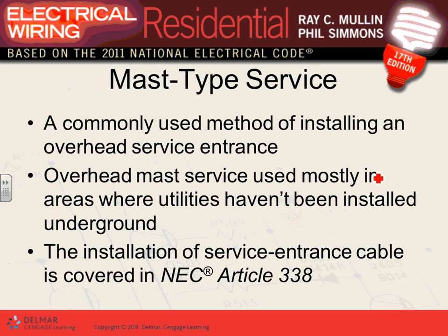Okay, mast type service. You guys have seen it all the time, that big rigid pipe that sits right here, and you bring the power lines to it. That's your mast, right? You've seen it if you walk around. A commonly used method of installing overhead service entrance for dwellings is to bring it to the top of that pole, mostly in areas where the utility has not installed underground. So that's coming from overhead.